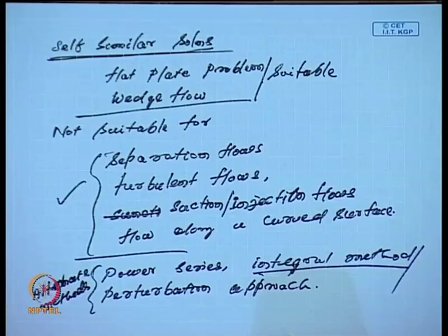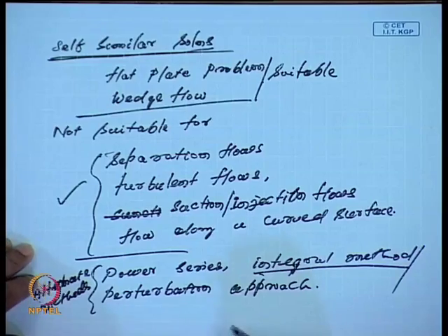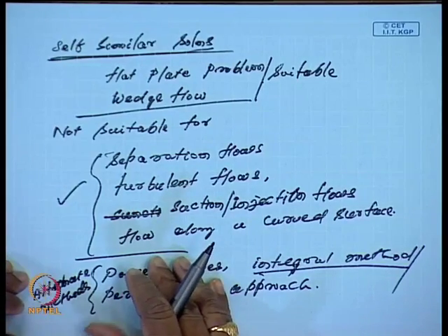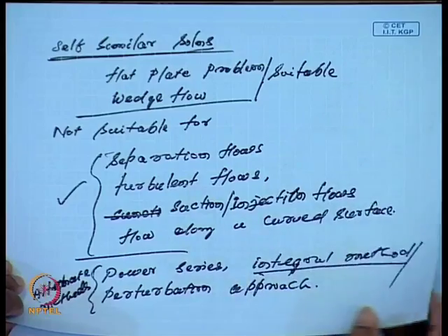So, with this understanding of the methods for solving boundary layer theory problems, we will not go into the details of other flow problems associated with the boundary layer. We have just briefly discussed what boundary layer theory is and the two dimensional governing equation, and then two approaches: one is the self similar solution approach, and then the momentum integral equation method, which is based on the weighted residue method.